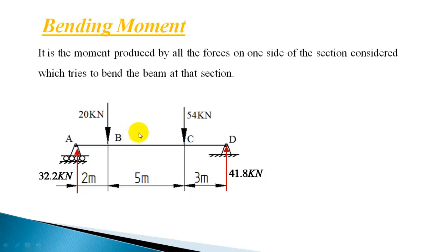Now the resultant moment, say M, if it is clockwise, and if you consider the right side forces, they will also produce a moment, and the summation of these moments will be counterclockwise and will have equal magnitude. If it is clockwise M from the left side, it will be counterclockwise M from the right side. So this portion of the beam is subjected to a bending like this, from left side clockwise and right side anti-clockwise. So they will be equal and opposite.